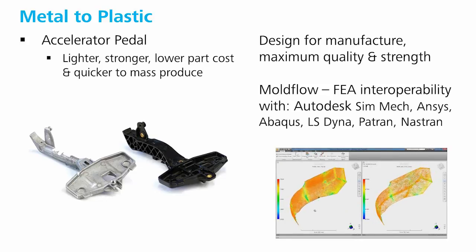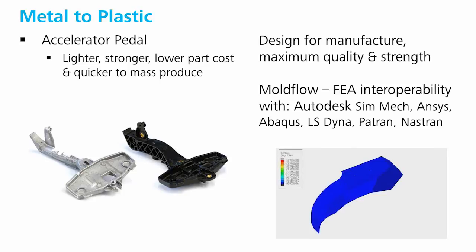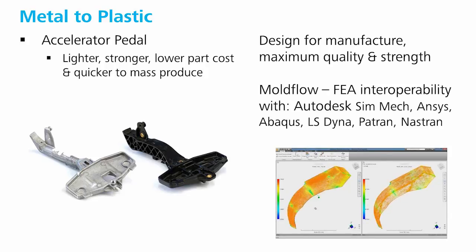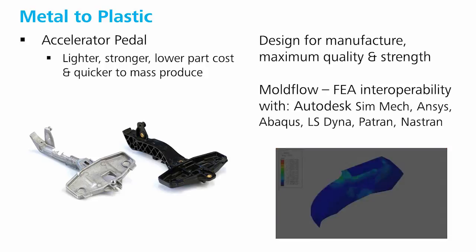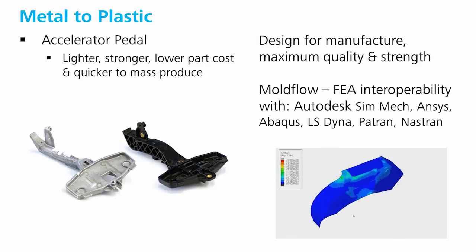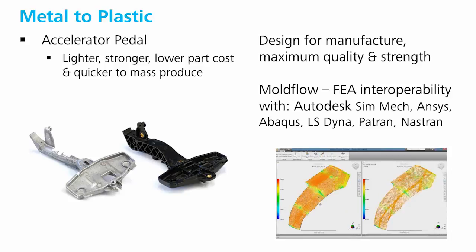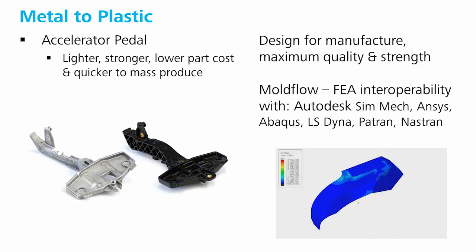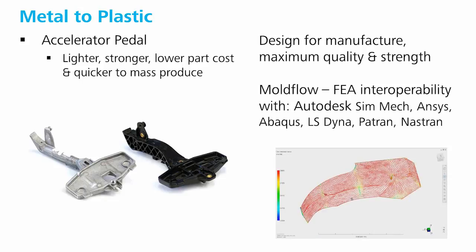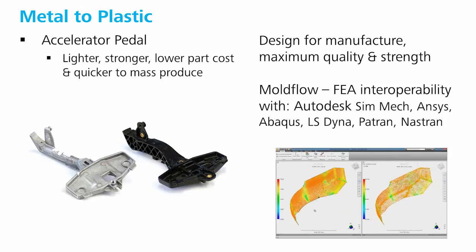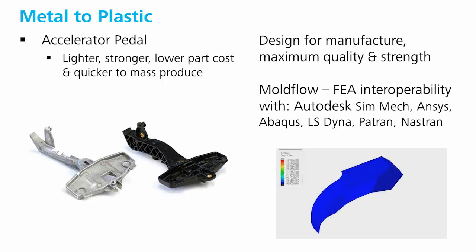So what we're passing on are the stresses from moulding. Plastic parts have internal stresses. Also, material properties change due to the moulding process, due to the orientation change of the molecules, and particularly if it's fibre filled for reinforcement, then the fibre orientation has a large effect on its mechanical properties. It could be stronger in some areas and weaker in others. Otherwise, structural analysis programs will assume constant material properties and no stress in the part.